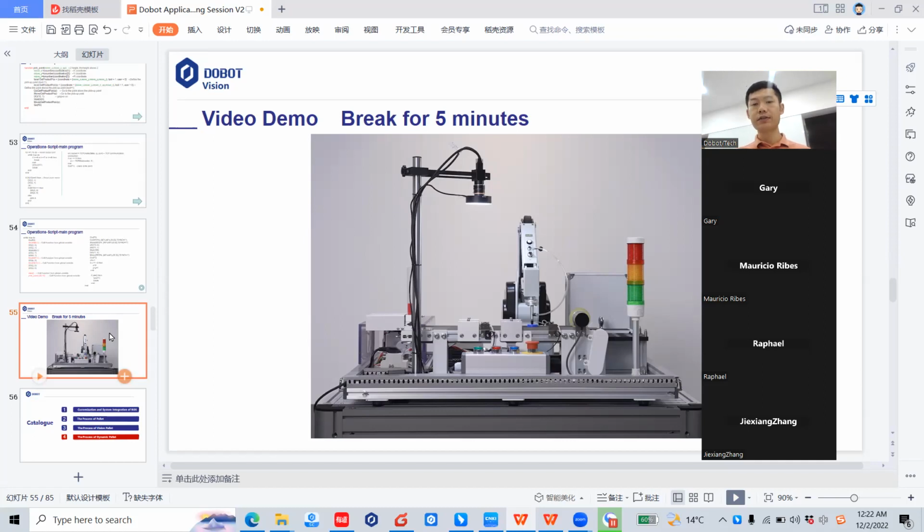I think there are two solutions. One is you use 3D vision, so you know how deep you're going to go. Okay, got it. The second solution, which we see a lot on CNC, is that the gripper has a spring on it. So if it touches here, it can compress a little bit, so it's not going to be a hard hit. I understand. Both solutions are possible.